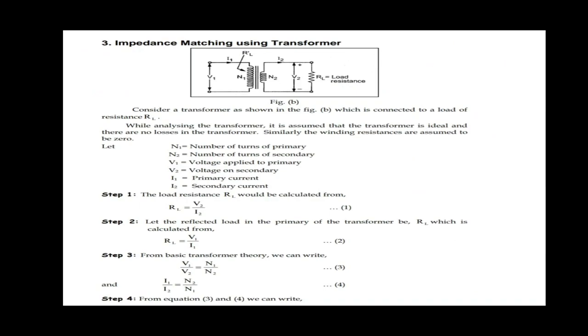So we have to discuss the operation. In order to get maximum AC output power, the peak value of collector current due to input signal alone should be equal to the zero signal collector current. To achieve this, the operating point is located in the center of the AC load line. The transistor remains in the active region throughout this operation. This is achieved by adjusting the biasing circuit R1, R2 and RA.